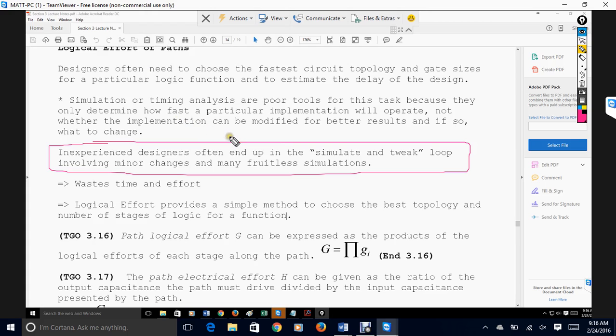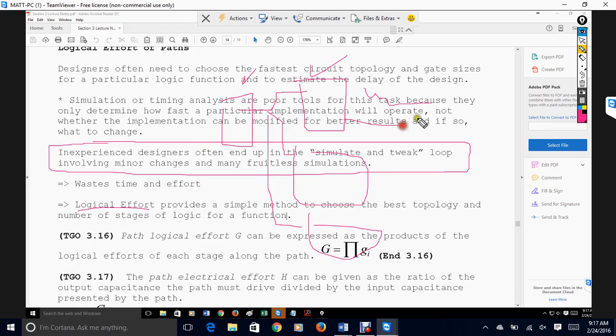So what ends up happening is designers get 2 cells that they think are going to work, right? And they tie them together like, oh, this is going to be great. And then suddenly the signal output sucks. And they have no idea why. This one worked, that one worked, what's wrong? You have to worry about this concept of logical effort and electrical effort. Because otherwise, if you're driving a number of these cells, the more that you add and the more you have downstream, it becomes problematic.